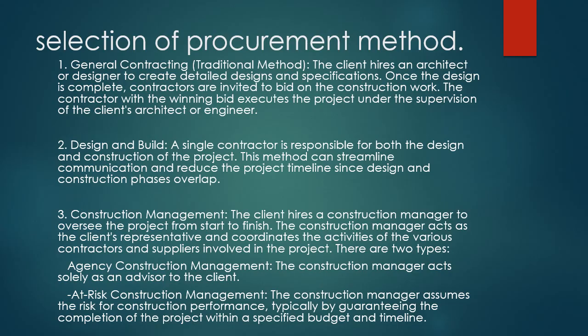Number 3, construction management. The client hires a construction manager to oversee the project from start to finish. The construction manager acts as the client's representative and coordinates the activities of the various contractors and suppliers involved in the project. There are two types: agency construction management, where the construction manager acts solely as an advisor to the client.